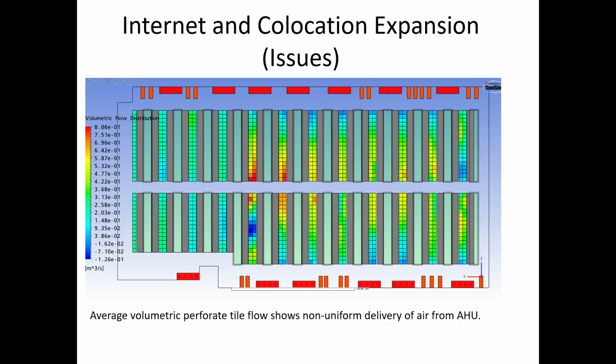Again, we have the highest flow rate because we have a perimeter design. These are the cooling units on the perimeter blowing down into the floor. And so just like in the earlier representation, we have best performance in the center. Furthermore, you see some variation in performance here. These are usually caused by local vortices, vortexes that occur. So here we have the air coming out of this one and the air coming out of this one. There's a slight bump out in the geometry of the room, and that's going to cause a general swirl here, and that will create a low pressure right in the center of it.